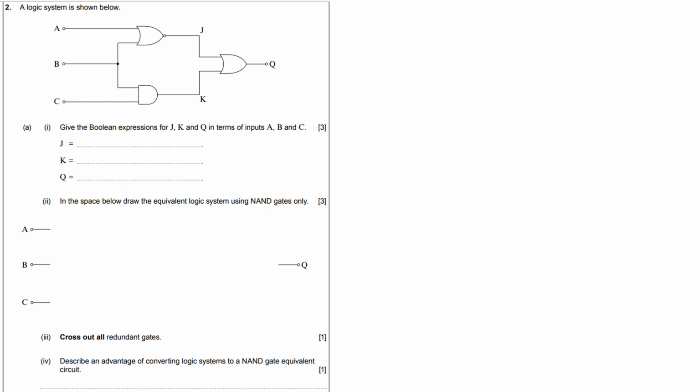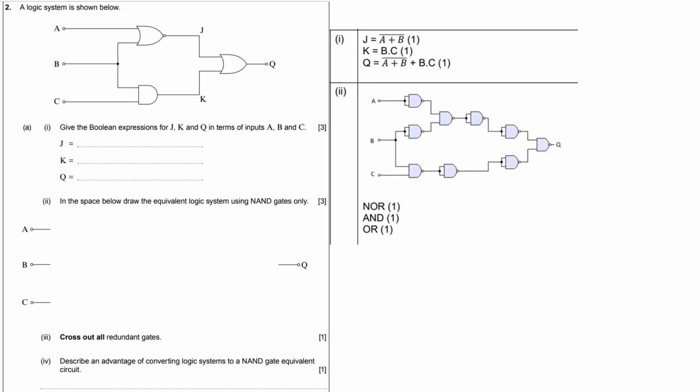Describe the benefit of converting to NANDs. Well, obviously you need fewer ICs, don't you, if you convert to NANDs? And in fact, you might be able to say exactly how many you would need. Oh, I've not actually written that on there. Sorry, cancel the 2 in the line, so that would cancel with that, and that would cancel with that as well. Okay, 1, 2, 3, 4, 5. You would need 2 ICs if it was NANDs. You would need 3 ICs without converting to NANDs.